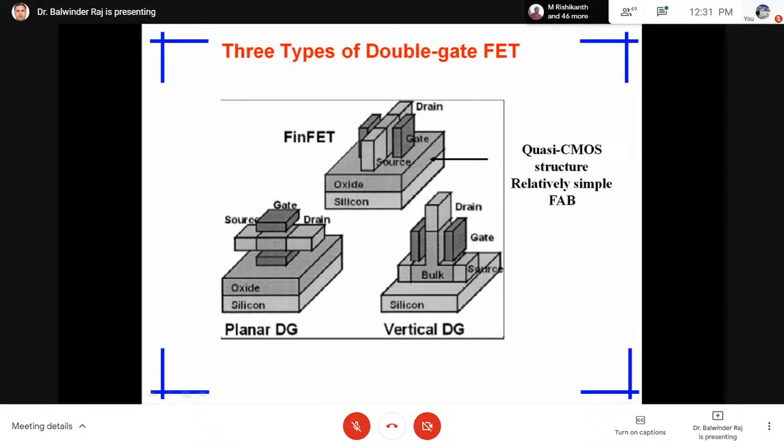This is the planar double gate, where planar technology is where we go layer by layer. It is also known as a serial type of fabrication. Sequentially, a number of steps are followed. Like we have to take the silicon substrate, grow the silicon dioxide, apply the mask, then there is ion implantation, doping, an etching process, deposition, chemical vapor deposition, then there is metal deposition.